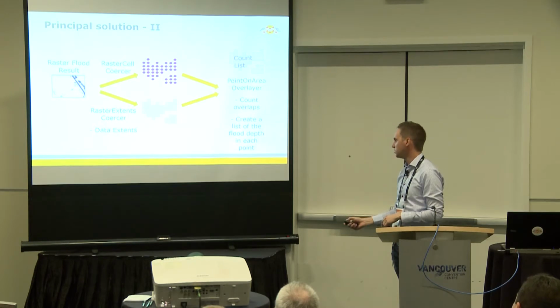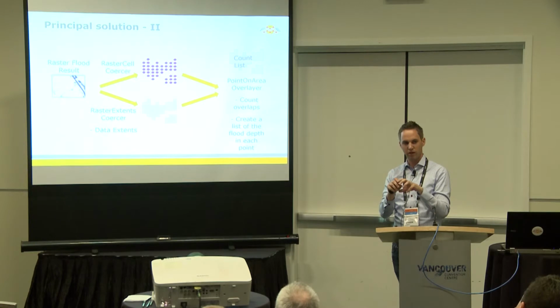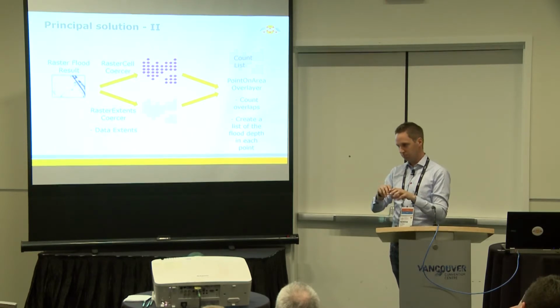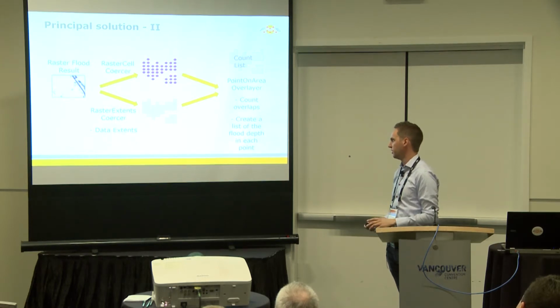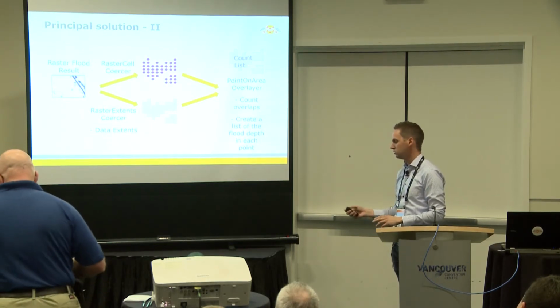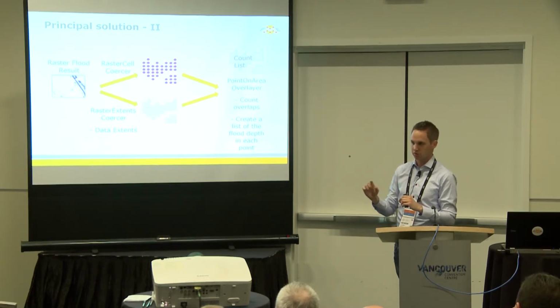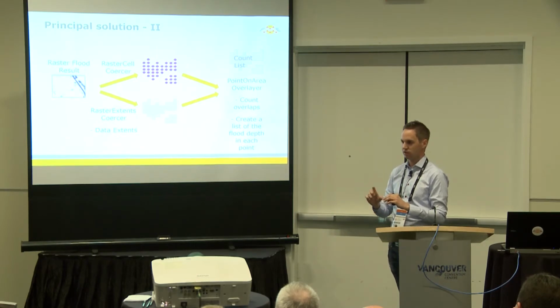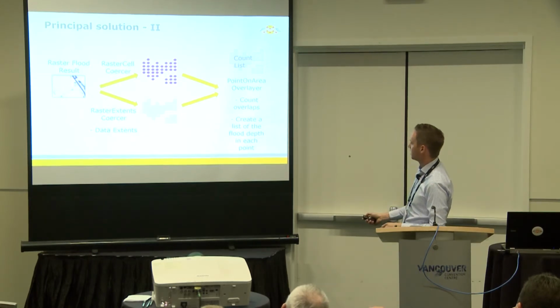But if you go into it and set it to data extents, you get polygons only for the areas where you have some type of value, and the no data values are just left as they are. And I can imagine that you could have some type of threshold. If you say everything beneath 2 centimeters of water, that's nothing I want to look at. That's okay flooding. You can just take the values and reduce it, and then you would also get a slightly smaller data extent area.